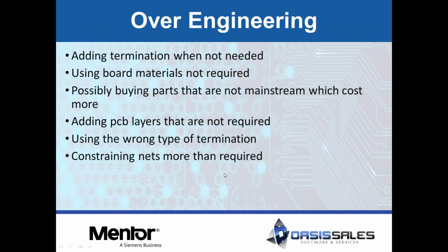Another place where quick simulation like this can help out is over engineering. A lot of data sheets or manufacturers may suggest you do things that may not apply to how you're using the part on your board. Maybe the traces are going to be longer than what they're showing in their reference designs. Maybe the board materials they're using are different, or they're specifying board materials that may be too expensive and you don't want to use them. So you won't know how it's going to affect things unless you play around inside of a simulation tool.